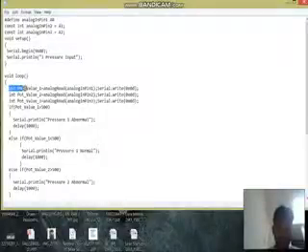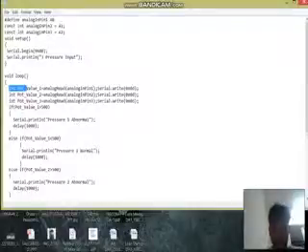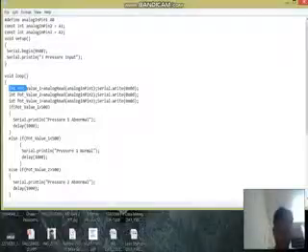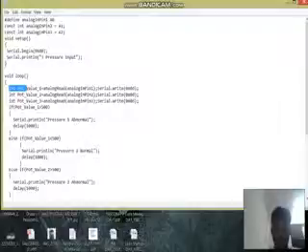As you can see, this is the code over here. Port value 1 equals analogRead of analog pin number 1, where we will be connecting pressure sensor 1. And in the same way, port value 2 will be connecting pressure sensor 2 in analog pin 2, and port value 3 will be connecting pressure sensor 3 in analog pin 3. And we have also given the serial write, and then we will be giving the conditions to all the pressure sensors.